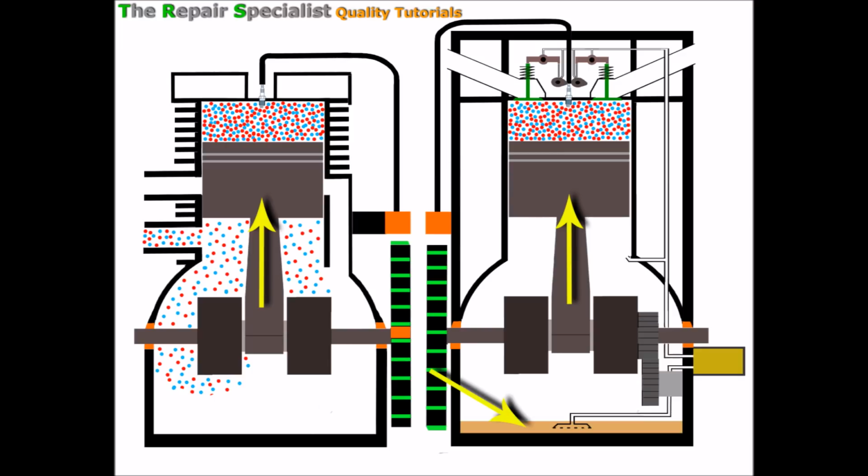As I mentioned before, the four-stroke has its own reservoir in the sump area, which is filled to the appropriate level with the appropriate oil. The difference is we keep the oil separate from the fuel on the four-stroke, and it's distributed around the engine via this pickup pipe, with the oil pump creating the flow. In the pickup pipe on this side of the oil pump, there's a vacuum sucking the oil in towards the pump, and then the oil goes through the pump and is forced out upwards, with positive pressure pushing the oil away from the pump.